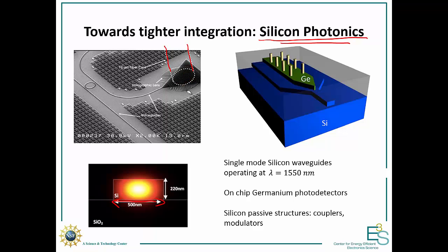right here, you've got a directional coupler, a grating coupler. And so what's going to happen is the light that comes onto your fiber is going to come here, and all these grates are made so that you scatter light and it all constructively interferes into a waveguide. So you're able to very efficiently couple light from an optical fiber into a waveguide here.